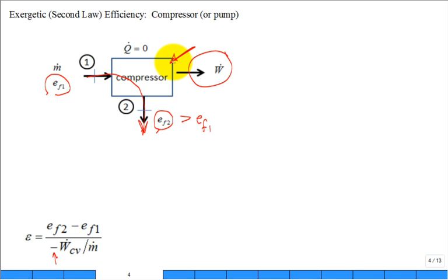That's my nature. I want to show it in. But I'm going to try and be consistent with the textbook. So you write an exergy balance equation. This time, we're going to write it like this. I'm going to put negative W dot. That's my in because of the shaft power. Where does it go? It goes into two places that are the outs on the exergy balance.